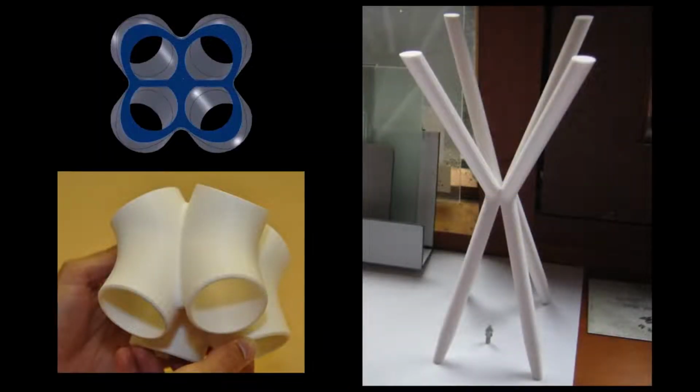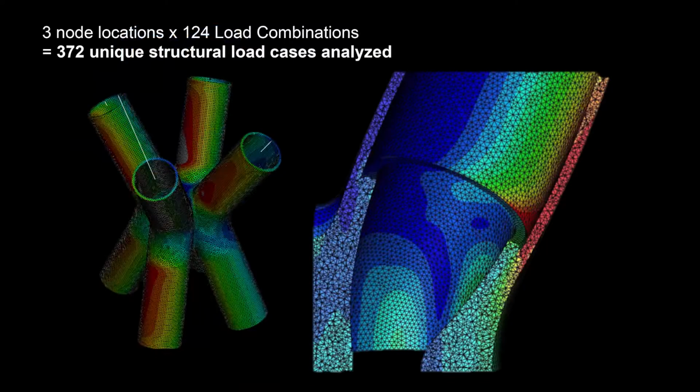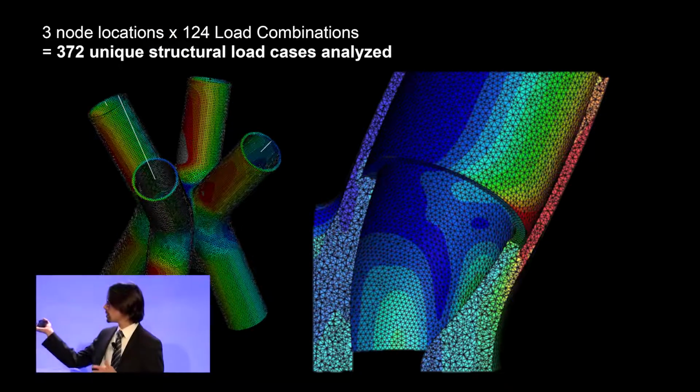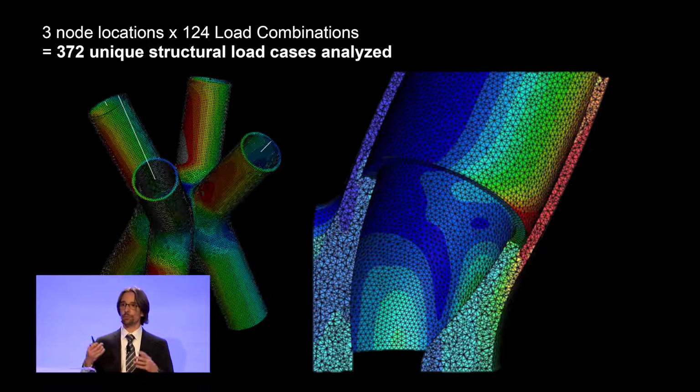And in fact, that's what we did, is we developed a cast steel node that would work at the center point of that delta frame. Of course, being structural, it has to be designed for all of the forces that are being applied on the node. You can see how we shape the interior to reduce the stresses through that cast steel connection. Again, putting the material where it ought to be for those flow forces.